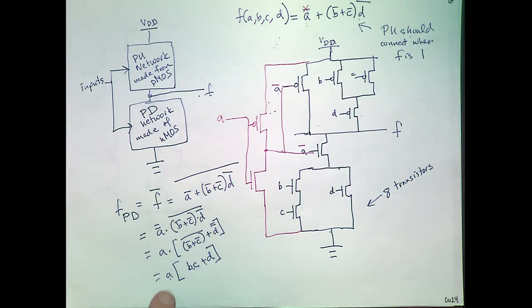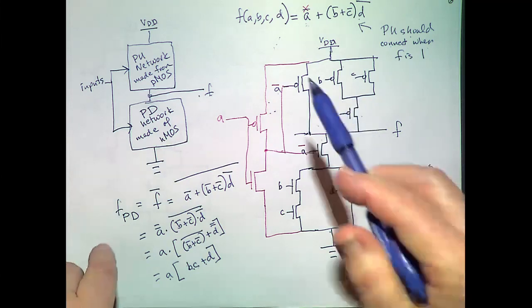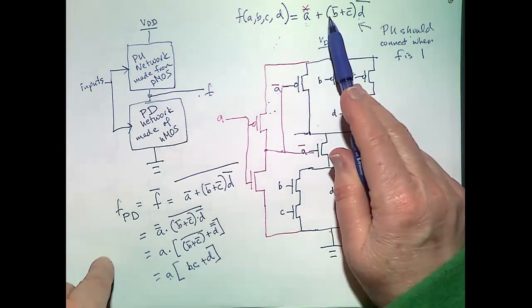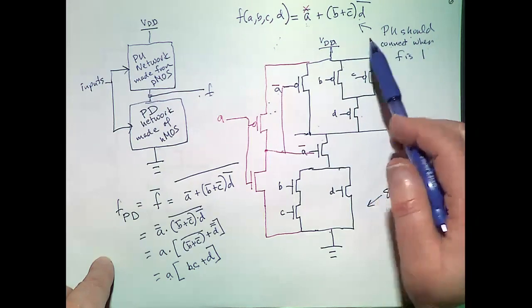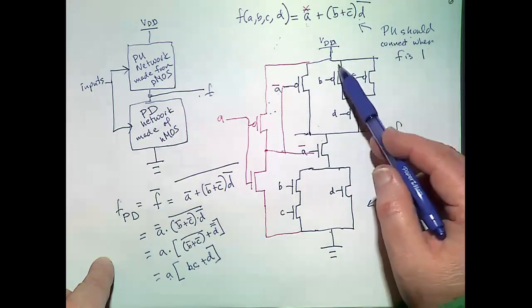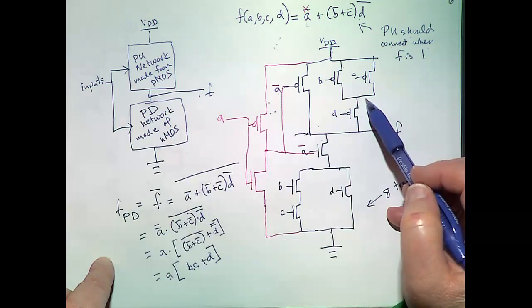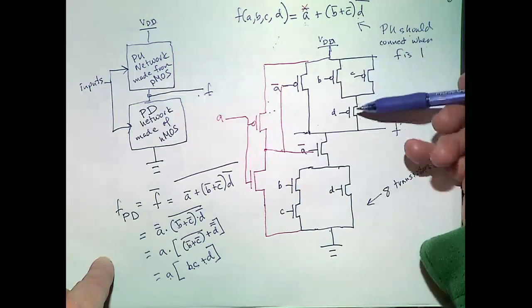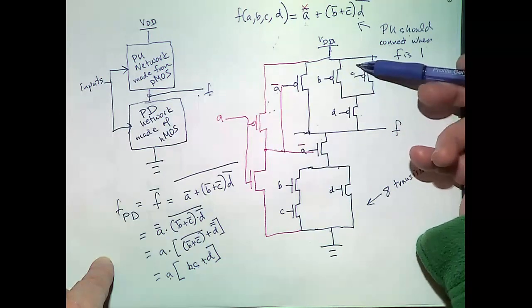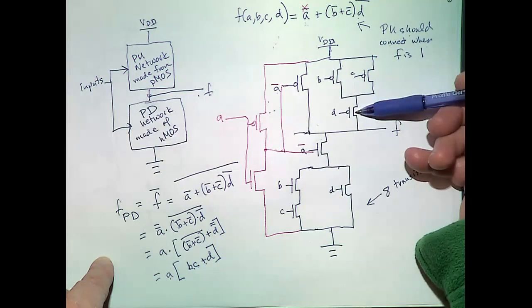We did this. Ignore the pink for the moment. That was a revision we did right at the end. We took our expression, and the original expression is pretty simple to create the pull-up network with. Wherever you have an OR, you want to provide paths in parallel, and whenever you have an AND, you want to provide paths in series because you need both parts to be conducting.